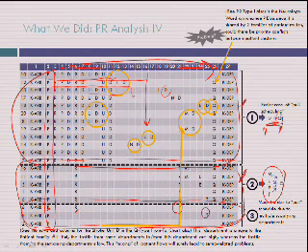And this is where I think pull mechanisms like Polca, finite capacity scheduling, constant work in process, drum buffer rope, are far more effective than what we've been told to believe is the Toyota way to pull. So knowing the complexity of scheduling can actually be gained from just applying production flow analysis. So that's how flexible and universal is the application of Burbidge's method.